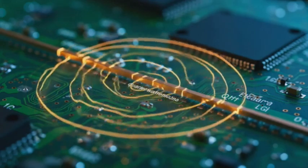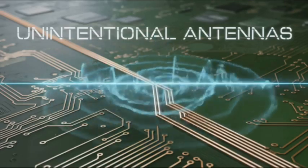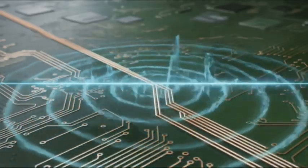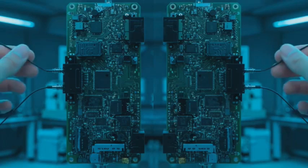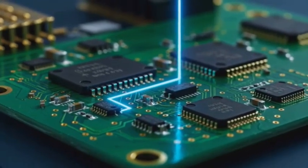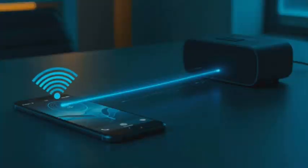Trace lengths around a quarter wavelength effectively act as antennas. A significant EMC challenge arises when PCB traces unintentionally become antennas, especially if there's a split in the ground plane. Antenna reciprocity means structures good at transmitting also excel at receiving, causing both emissions and susceptibility issues. Intentionally designed antennas, such as Bluetooth antennas, often use this same principle deliberately.